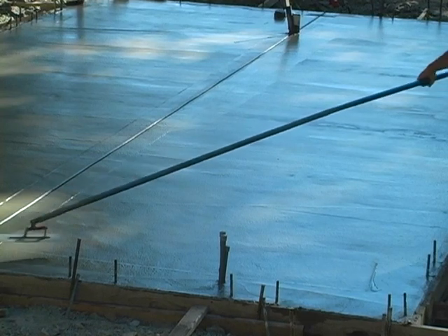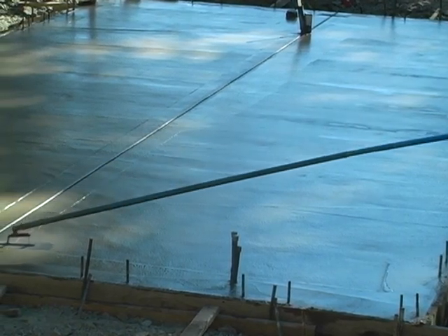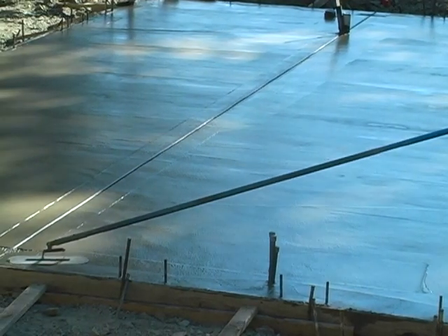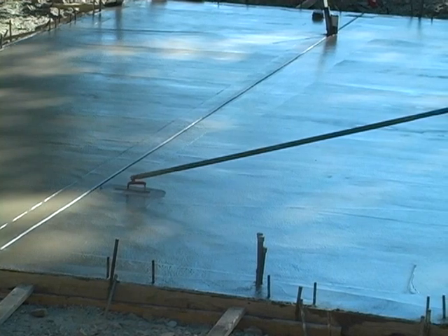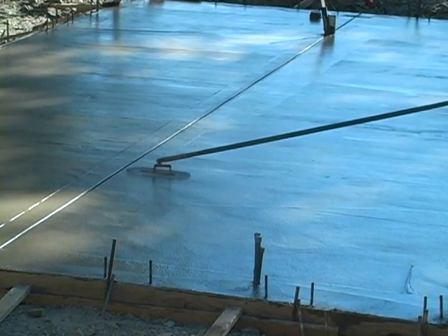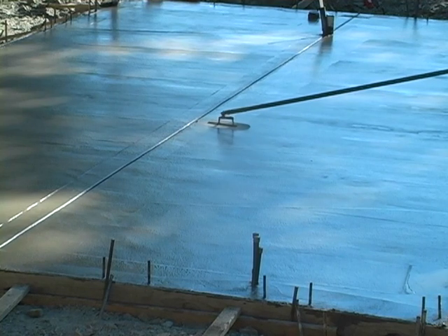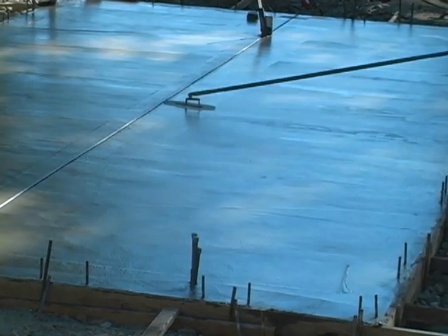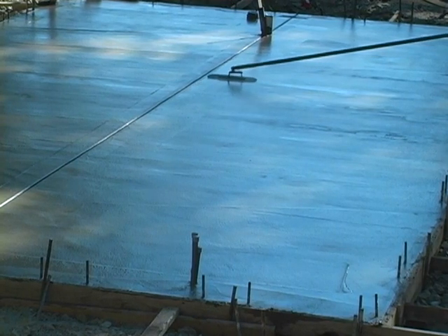And we're using a trowel here on an extension pole, which takes quite a bit of skill to do. You want to set it down and then give it just a little bit of a twist so that it lifts the front end of the trowel up as you're sliding it across. And by using the steel trowel out on the extension pole, you can clean off those lines and get a nice clean groove right down the middle without any representation of where the outside of the plate was.